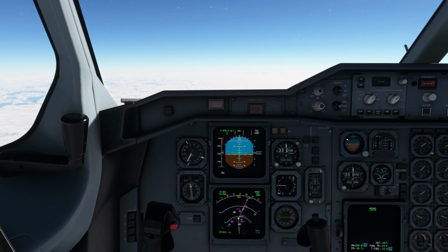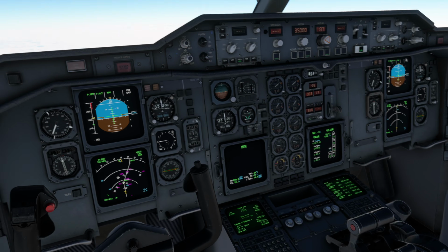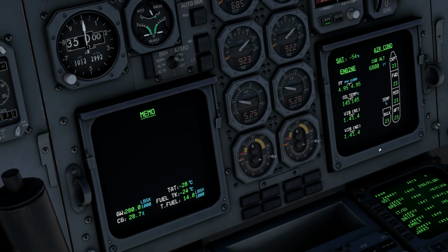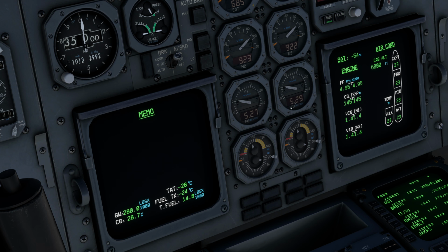Finally, as we are flying along, we also want to compare our fuel burn with our flight plan. And we basically do that once every 30 minutes, but latest once every 60 minutes by comparing what we are burning and how much fuel we have used, adding that up. So for example, we can say our fuel used over here is now roughly 10.6. So we've used 10,600 pounds of fuel.